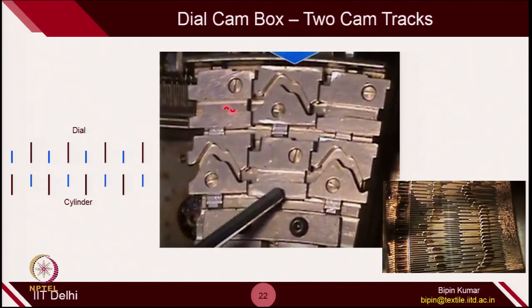Here it is first resting, then it is doing knitting, then again resting. But when the dial short butt needle is resting, you can see the long butt needle is in active position. When the dial short butt needle is active here, then the dial long butt needle is resting. This is how the timing and the sequence of needle movement on each of the beds is decided.